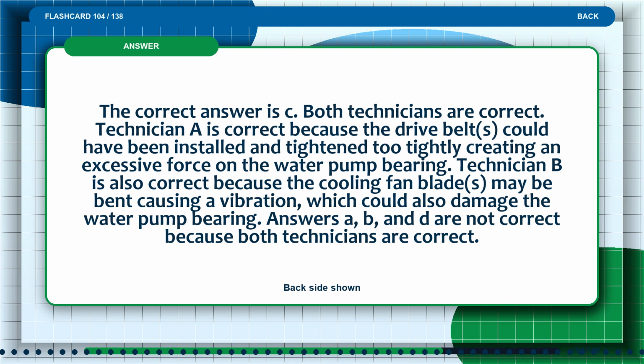The correct answer is C. Both technicians are correct. Technician A is correct because the drive belt could have been installed and tightened too tightly, creating an excessive force on the water pump bearing. Technician B is also correct because the cooling fan blade may be bent, causing a vibration, which could also damage the water pump bearing. Answers A, B, and D are not correct because both technicians are correct.